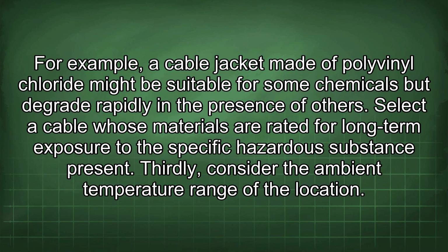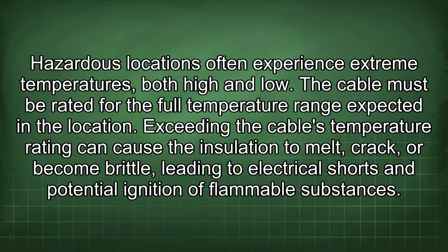Thirdly, consider the ambient temperature range of the location. Hazardous locations often experience extreme temperatures, both high and low. The cable must be rated for the full temperature range expected in the location. Exceeding the cable's temperature rating can cause the insulation to melt, crack, or become brittle, leading to electrical shorts and potential ignition of flammable substances.